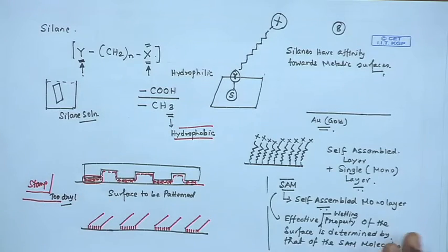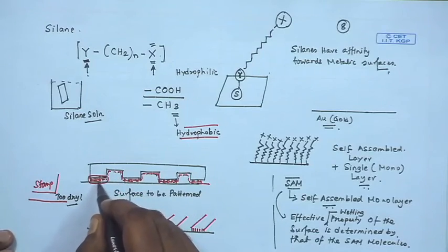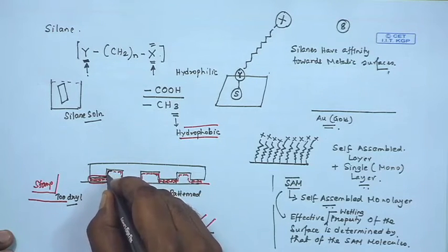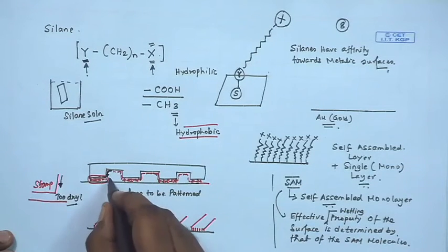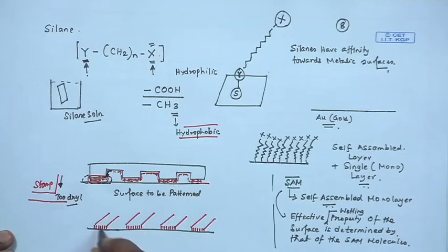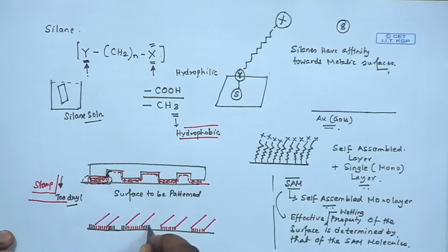On the other hand, if it is too dilute, if it is too wet, what will happen is that the silane molecules will transfer, but in fact the liquid tries to drain off from these areas, and as a consequence these patterns will try to smear out. You will get transfer, but you will get additional transfer of molecules beyond the width of the original stamp pattern. So, your feature size becomes large.